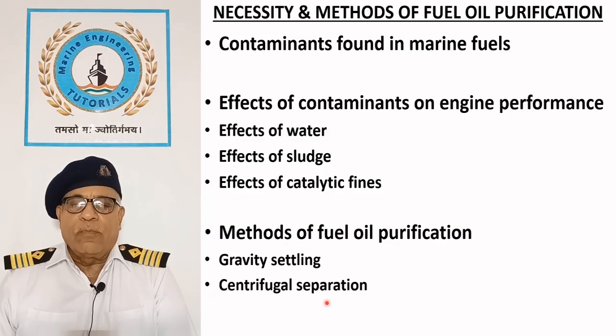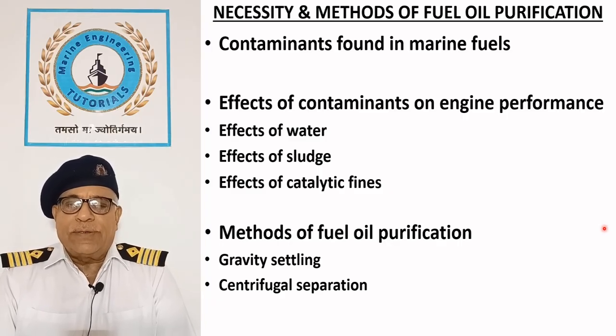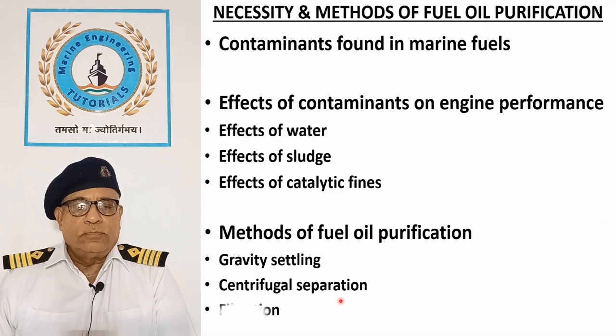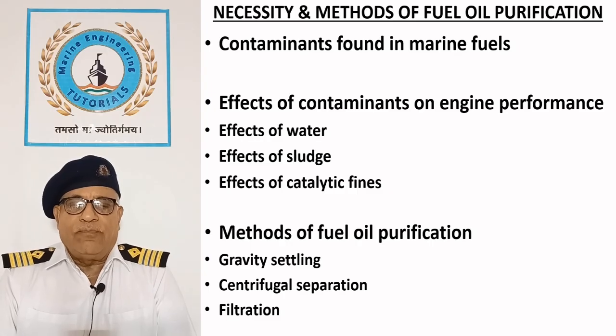Centrifugal separation. It uses centrifugal force to separate components of different densities. It is a fast and continuous process to remove water and solids from fuel. Filtration. Filtration is the final stage of fuel cleaning before injection in the engine cylinder. Filtration can remove particles as small as 10 to 25 microns in fine filters.